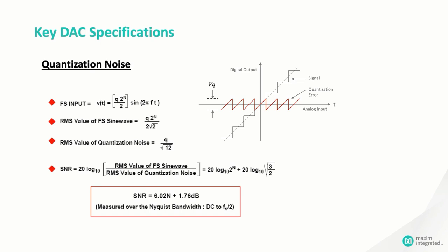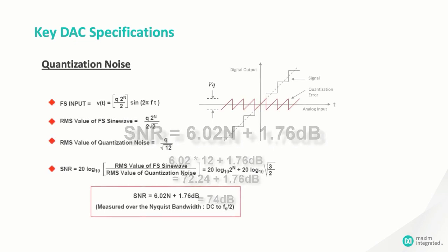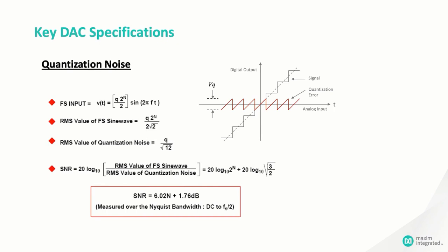The signal to quantization noise ratio is always 1.76 dB plus the number of bits of resolution in the DAC times 6.02 dB. In a 12-bit DAC, the SNR due to quantization noise is 74 dB, and that means a 12-bit DAC will never have a better overall signal-to-noise ratio than 74 dB, since the quantization noise is baked into the sampling scheme. Now, both harmonic distortion and quantization noise tend to push the output away from the ideal values that we'd like to see.